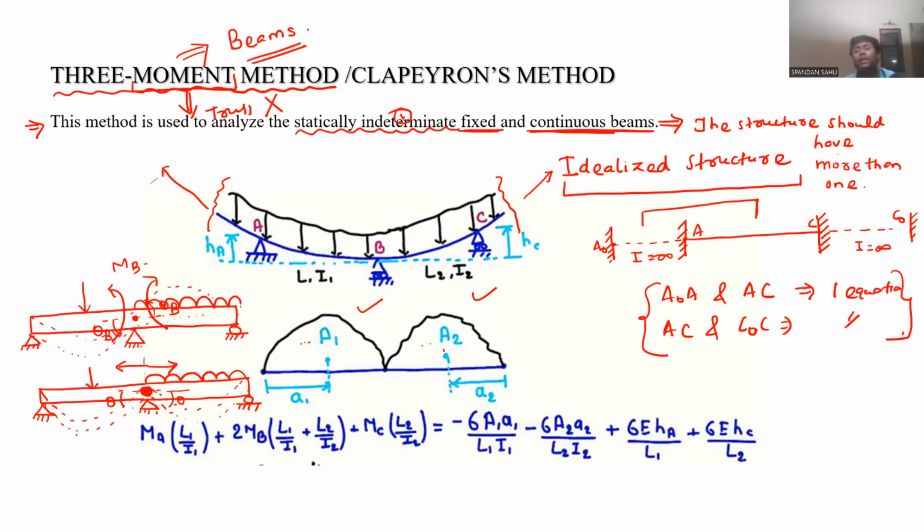Now, what are we doing in the force method? We apply unit force or unit moment, depending upon the type of redundant we have chosen.